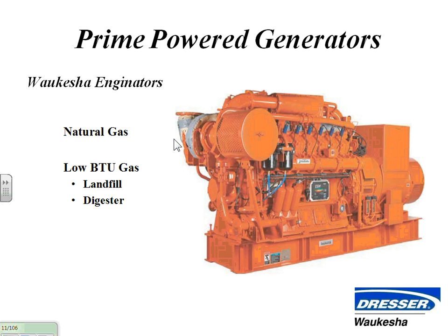I sold one of these most recently down in the city of Rochester. They take the gas off the wastewater treatment plant, the methane gas, clean it, and run it through and power the engine with it. So they have a cheap fuel source, and they take the output of the generator portion of that, and they run the plant in Rochester. And also they take the heat off the exhaust and off the water jacket, and they use that for part of their process. So it's called cogeneration in its truest sense.